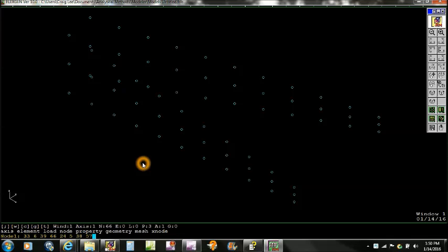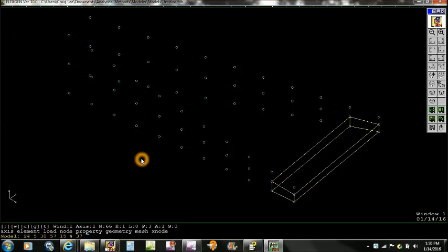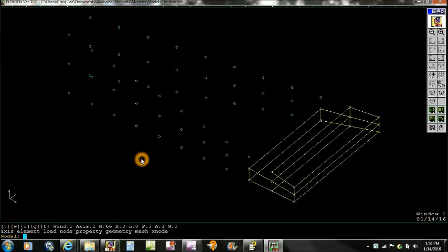And now we start. We could either select the nodes by clicking on them with a little trap box here, or you can just pound in the node numbers. For the purposes of the demonstration here, I just put in the node numbers, and that creates the first element, and then again the second element, and now a third element.